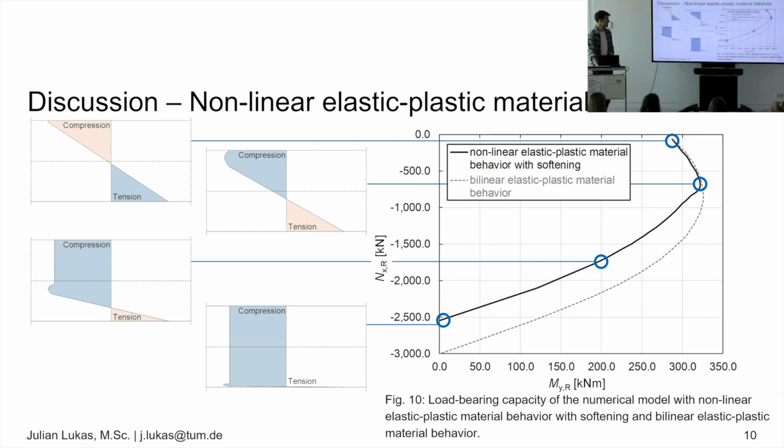And that's how it looks at the end. And that doesn't really look right. I get immediately no tension on the side, but I still say, okay, I have tension failure. And my whole beam is under compression, which doesn't make sense, because in that case, we are looking, for example, into the same cases I told you earlier. I look at a pure compression test where I should have a straight compression at the maximum. That's why this doesn't make sense.